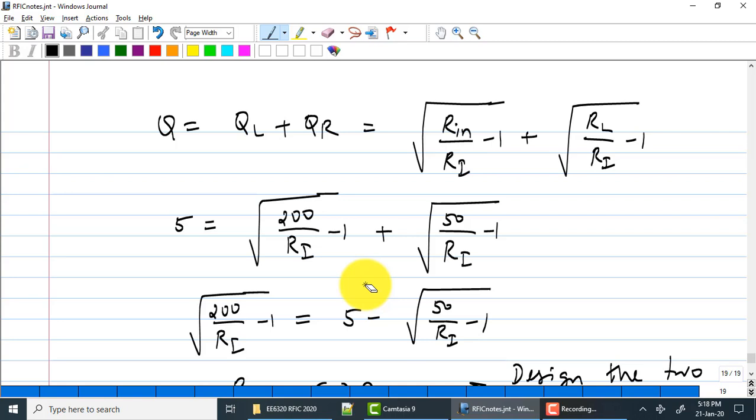Just like you create a capacitor by putting a dielectric. Right? So epsilon naught, epsilon R times area of the plates over distance between the plates. If you don't put a dielectric, right, the density will be lower, epsilon R is 1, you only have epsilon naught. Similar to that, if you actually wind a wire around a magnetic core, the relative permeability of the magnetic core will actually improve the inductance for a given number of turns. If you don't do that, if you just do it around air core, you do have air core inductors, you will get a much smaller inductance for a given area, which is what happens on the integrated circuit. You do not have a magnetic material. Okay, so you pretty much just wind it around air.